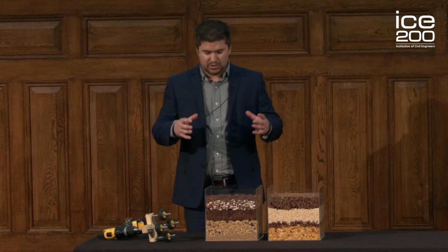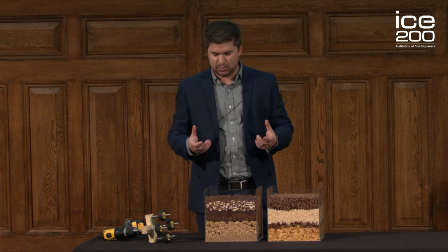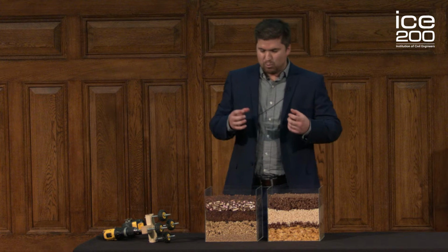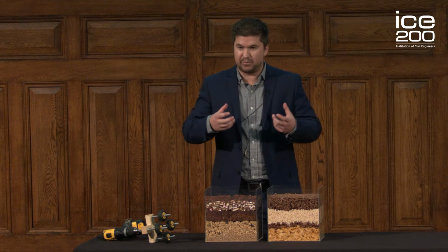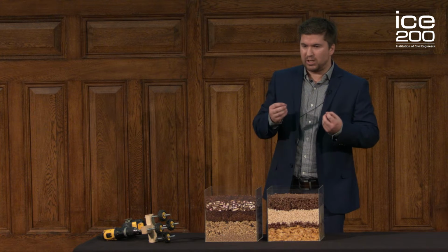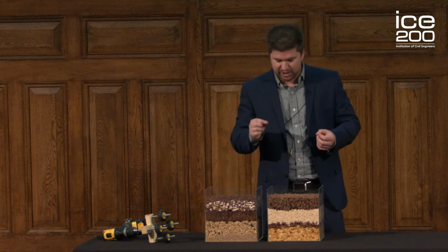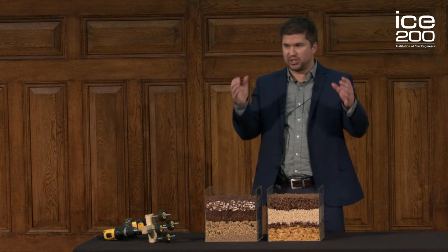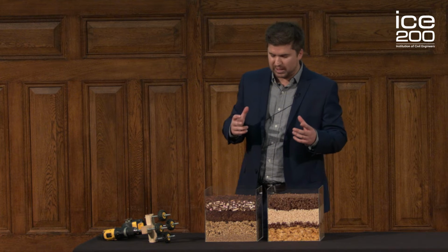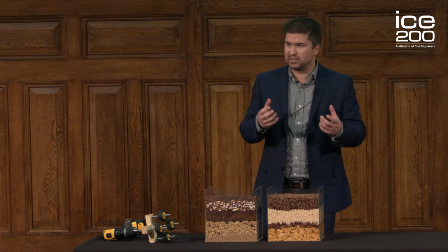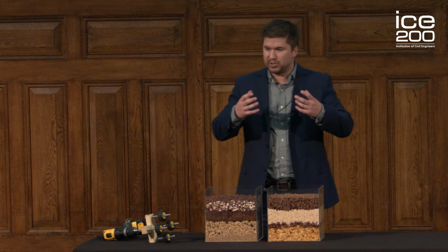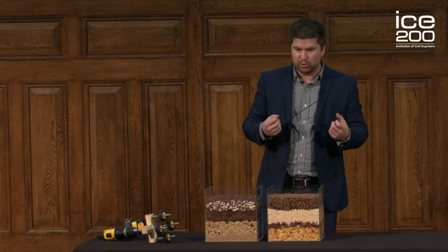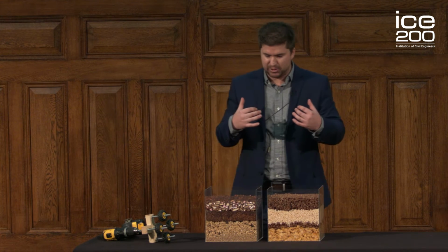So every pavement starts with the existing soil, or the subgrade as we term it. In the example of the poor pavement here, we've got something that's very heavy in clay. So clay particles, whilst they're very small, they're shaped like cornflakes. So they have a large surface area, and this, coupled with the fact that they have imbalanced electrical charge, means they hold a lot of water. And what happens is over time that water drains from the soil, and the pavement overlying that collapses above it.